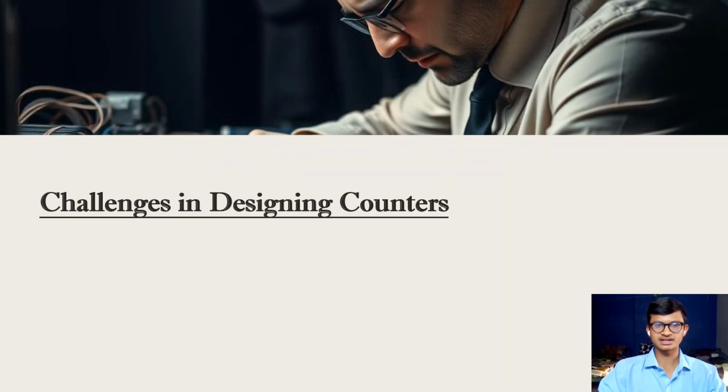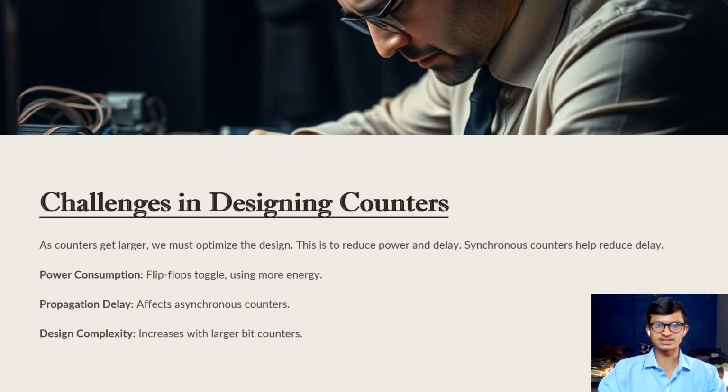When designing digital counters, there are a few key challenges we often face. One is power consumption. Every time a flip-flop toggles, it uses energy. In large counters with many flip-flops, this can lead to high power usage, especially in systems where energy efficiency is important.